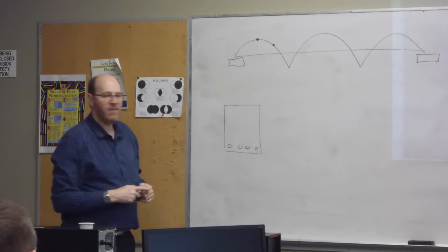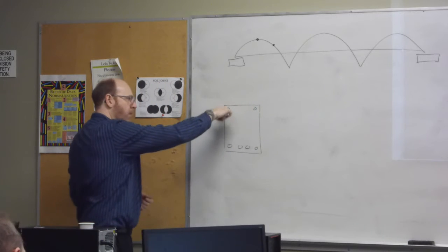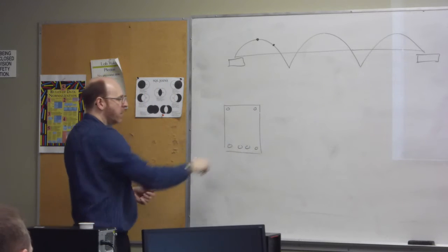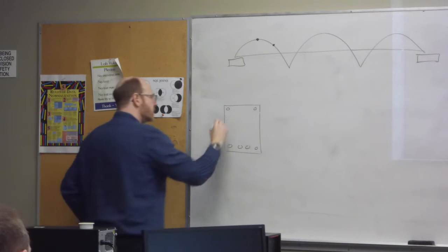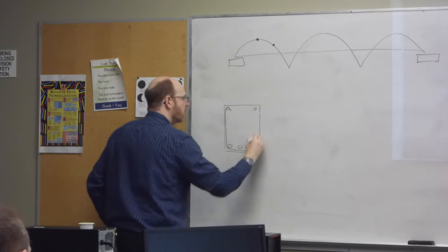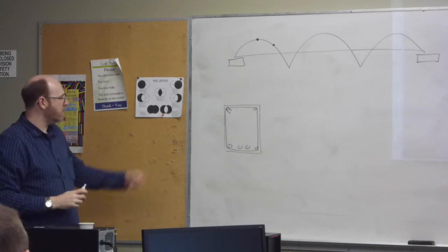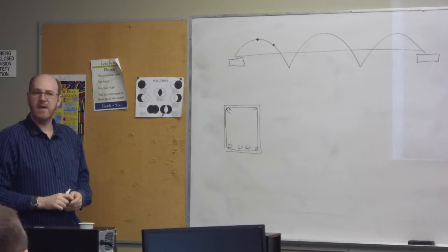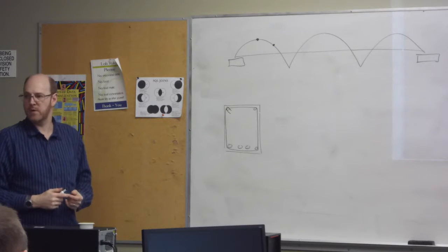So we're going to have, at a minimum, 2 bars in each corner, so a bar in each corner, 2 bars top, 2 bars bottom, that run continuous over the entire length. This allows us to put in our stirrups, assuming that we have stirrups in our beam. And we now have enough to be able to build that steel cage. So at a minimum, we're going to have a bar in each corner to do that.